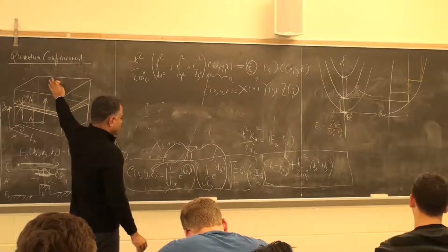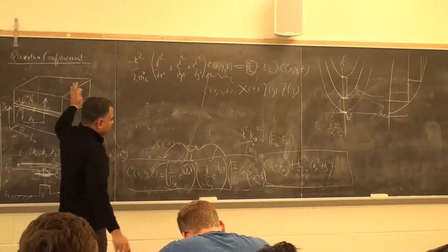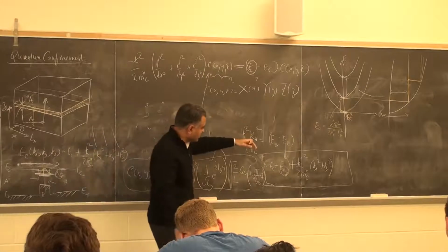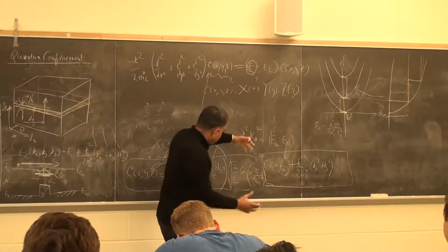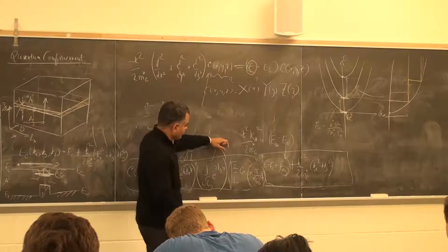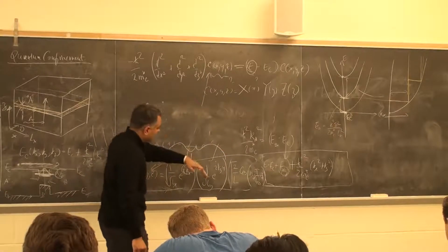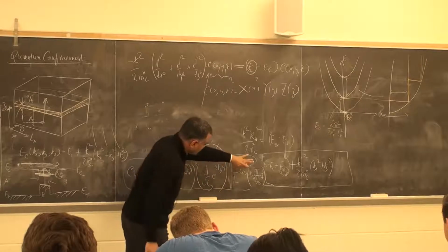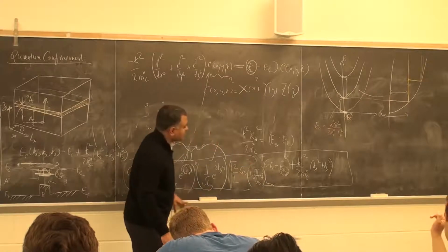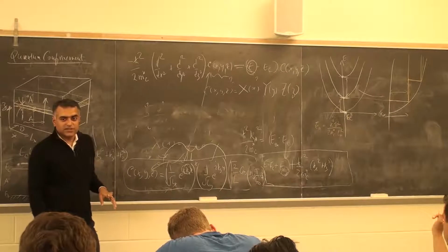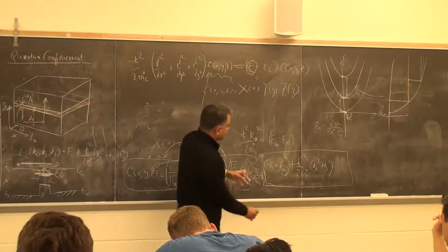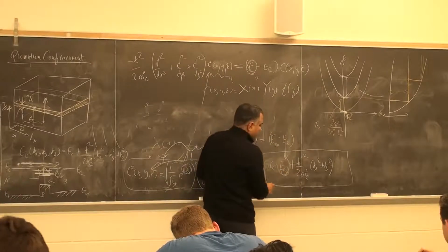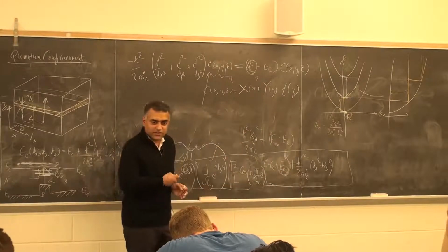I started with the effective mass equation. We looked at the 3D problem, and we said it should be complex exponentials in all directions, and energy would be just like a free electron in all directions, but with a slightly modified effective mass. Now you add quantum confinement in one direction, and in that direction the envelope function becomes bound state functions. Therefore the energies for that direction in which you quantize become bound states. It has no k, effectively. It doesn't have a free k.